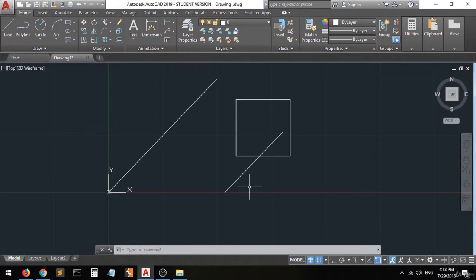Okay? Now, as you can see, using the at sign will do it relative to the start point. Okay? But when you don't use the at sign, it will be calculated from the origin. Be careful. So, if you do this, select the line and then specify the first point, not picking any point from here.